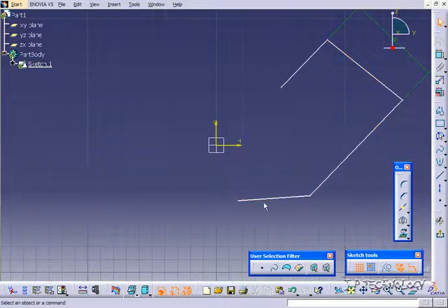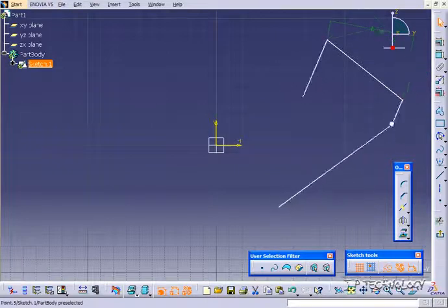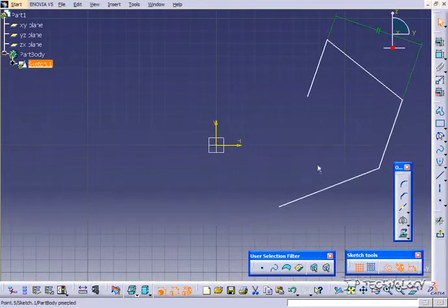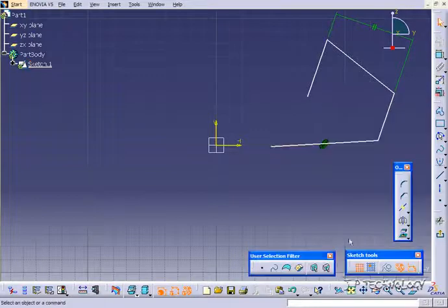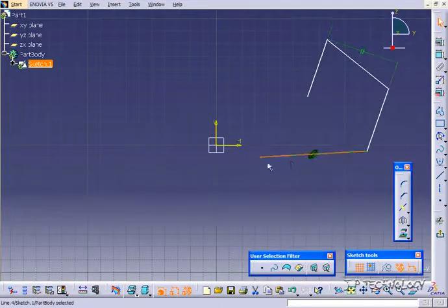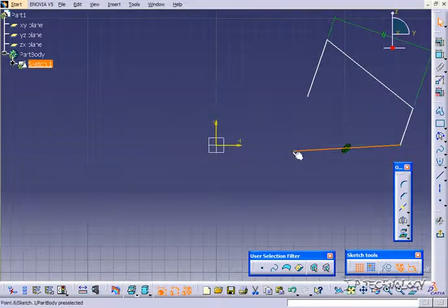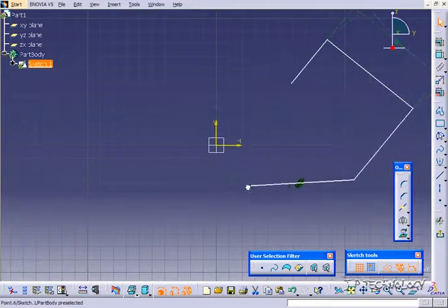If you remember how to use the manual sketch editing, you can just grab a point and move it, bend it, twist it. You're able to do that to all the lines on here. Now what's going to happen if we fix together this line here? So let's click Fix, and we'll click the line, click OK. And you'll see that we can't drag and change the dimension of this line.